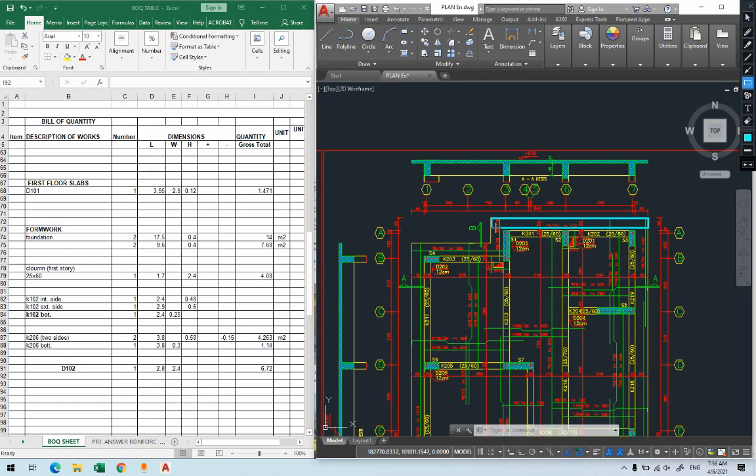Look, you calculate this area. You calculate this area around, this is extra, 20 centimeters will go out. This is the area where you put formwork under it. That's why you calculate only the area of the slab. That's why it's easy to calculate formwork for a slab. You just need to calculate the area.